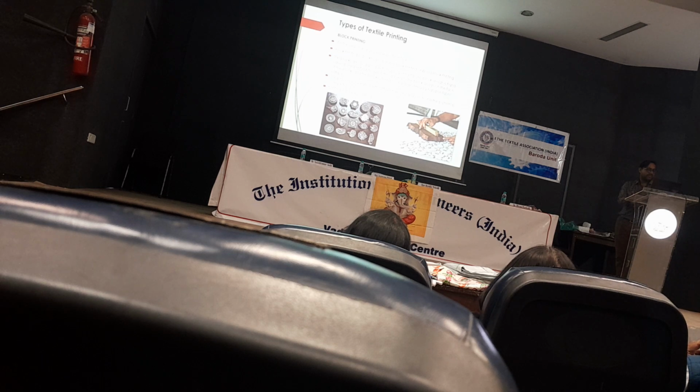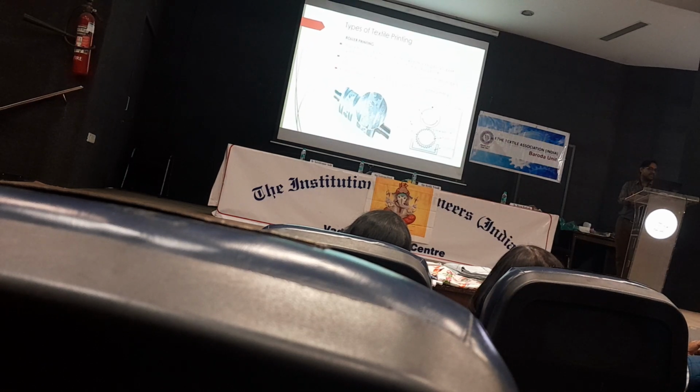The print paste dye stuff is applied to the block design on the face of the block, and the block is then pressed down firmly by hand on the fabric surface. The process is repeated with different designs and colors until the pattern is completed, and the process is totally manual. Roller printing is the advanced, machine version of block printing. It's not very different compared to screen printing.